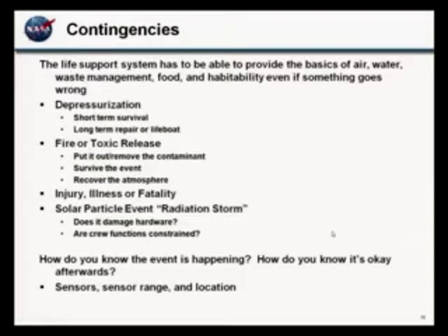Halon does some really nasty things in the high temperature catalytic oxygen or oxidation beds we typically use. Carbon dioxide is a little better because at least we have carbon dioxide removal systems already, but that's a lot of carbon dioxide you just pumped out. Water vapor, again, we have water removal systems, but that could be a pretty significant load you need to remove to get your habitat back to normal.